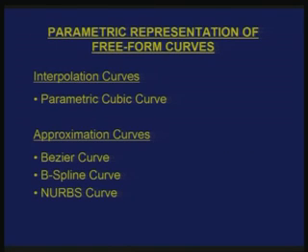Now, I will come back to our major subject of study here, which is concerned with freeform curves. And in freeform curves, as I said, we will be studying under two categories. One is interpolation curves and second is approximation curves. So, we will start with first interpolation curve, and one of the very common curves in this category is called a Hermite curve, or it is also called a parametric cubic curve.